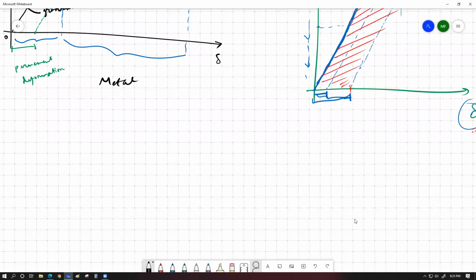One is the metallic bond. Metals are very ductile, and they are also very malleable. These are two words that pretty much mean the same thing, but under two different types of effect. Ductility of a material refers to the ability to become thin wires, or to have a large plastic deformation region before breaking. That's important.